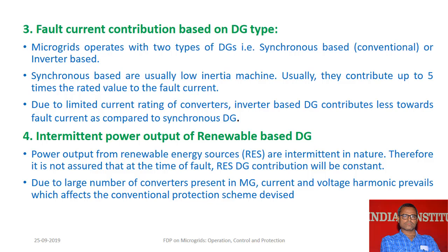I'll give an example of transformer harmonics, the magnetizing inrush in a transformer. That also is seen by the relay as a fault current, but actually it consists of many harmonics and DC components, right? So in a transformer we put the harmonic restraint percentage biasing relay, right? In that case, due to the harmonic current, a restraint is created, which doesn't allow the differential relay to operate during the magnetizing inrush.